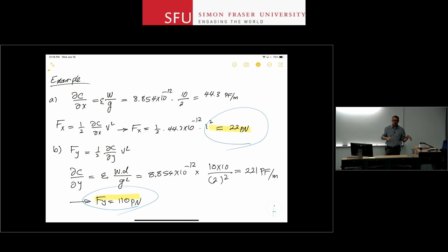For MEMS, once you put the two electrodes close to each other after the lithography step, you still have to etch the structure. You have to go into the substrate and create that gap. And that etching step tends to be much more tricky than the lithography step. With lithography, I can get these kinds of gaps easily, but going deep into the substrate and maintaining that gap turns out to be a significant challenge.